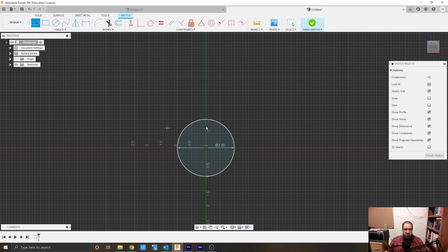So it's cutting this circle in half, and we're going to utilize this trim tool to trim across it. Now you'll notice we can see that there's a blue line here, so we can tell that that's not set per se. But what we're going to do is make this line coincident with the center point, our origin point. So that's our half moon.